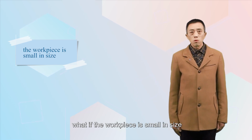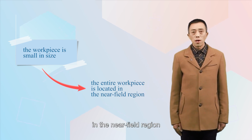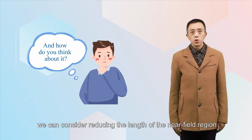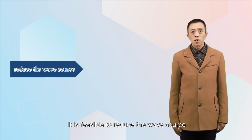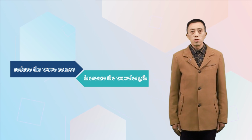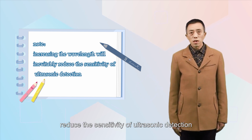However, what if the workpiece is small in size and the entire workpiece is located in the near-field region? At this time, we can consider reducing the length of the near-field region. According to the previous expression of the length of the near-field region, it is feasible to reduce the wave source and increase the wavelength. It should be noted that increasing the wavelength will inevitably reduce the sensitivity of ultrasonic detection.